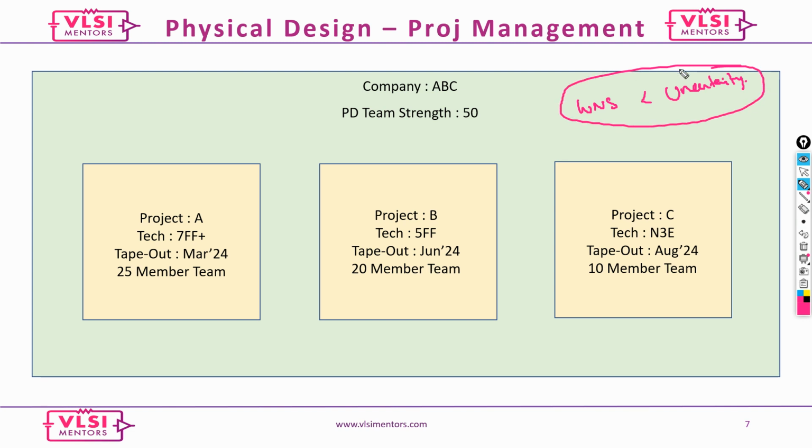But again, it depends on what kind of path, what kind of cells are used in that path, how long the path is, how the placement of that path is, and how the routing happened. So there are many other things before we say anything. But the preferred, I treat it like WNS should be less than uncertainty to move forward, or you can say off of your uncertainty. So it purely depends on the design.